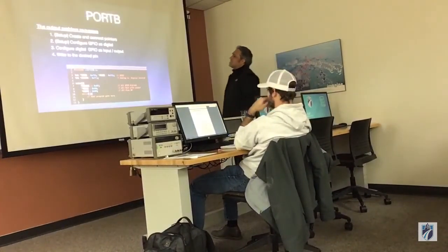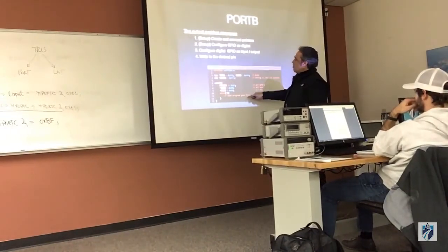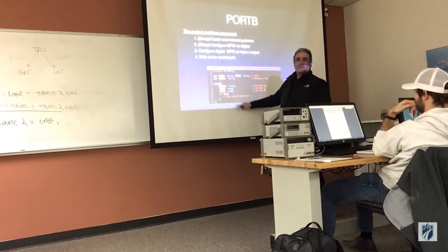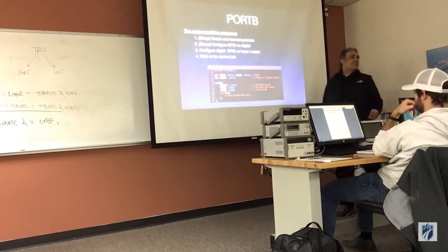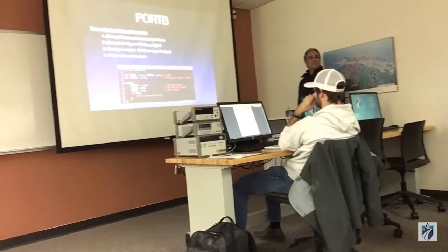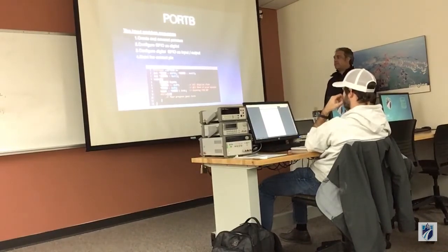So now that means that if you're going to do some sort of output on port B, you also have to do a digital output to it. Right? The formula for port A and port B is exactly the same. See that? Any questions on this? Input is the same. Digital input followed by read. It's always the same.